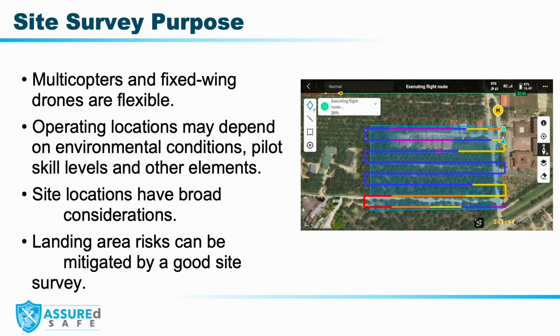The selection of a platform in pre-mission planning will drive site selection for an appropriate takeoff and landing area. While there are few operating limitations for drones, the major exception is that fixed-wing aircraft require a launch and landing path to accommodate their takeoff and landing slope angles. Though some newer platforms are able to shorten this requirement with more aggressive maneuvering, the requirement for a clear area will still be greater than for a multi-rotor aircraft.